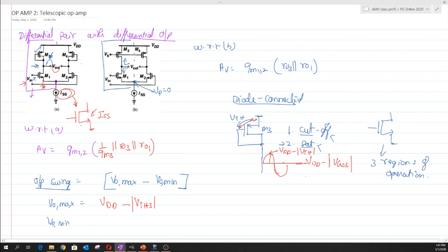What I mean here is that let us label this structure that realizes this ISS as transistor M5, and we know that there is a minimum voltage drop across the drain and the source that has to be maintained such that M5 is operated in the saturation regime. This ISS can be realized either as a simple structure like this, or as a cascode configuration, or whatever configuration we discussed when we discussed the current mirror can be utilized as a tail current source at this point.